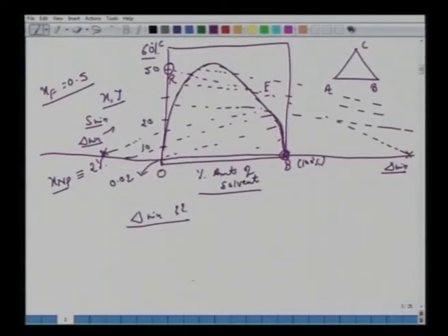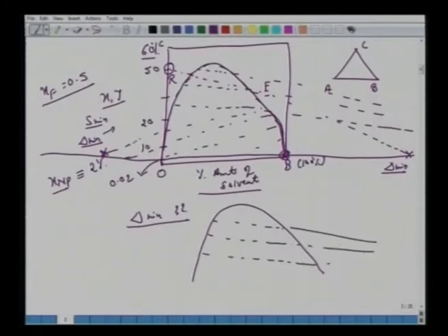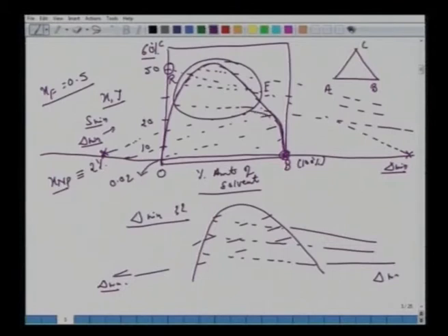Here there are some tie lines at the lower concentrations and some at the higher concentrations where the slopes are different. So in principle, one has to calculate what is the S min required from here, and what is the S min required from here. Any of these two will give you an S min. You have to compare the two and find out which is the maximum of the two, so that when we take the larger amount, we are on the safer side. Now suppose you work on this and you calculate S min.